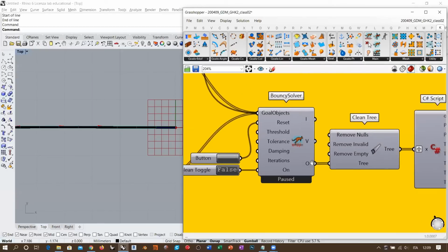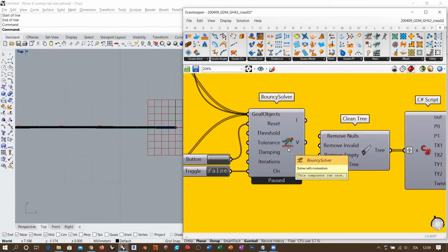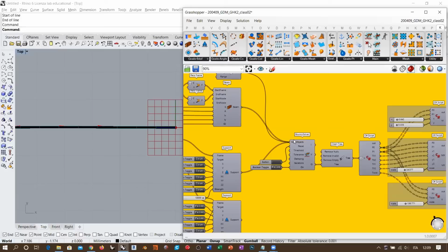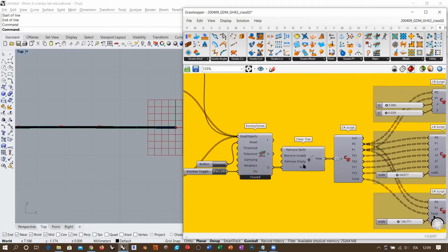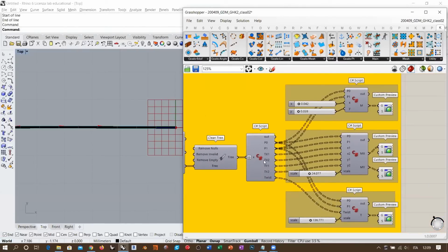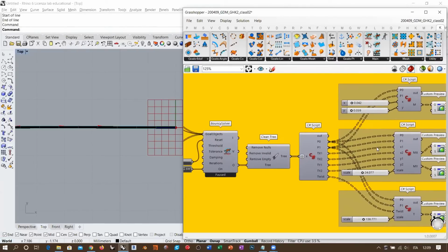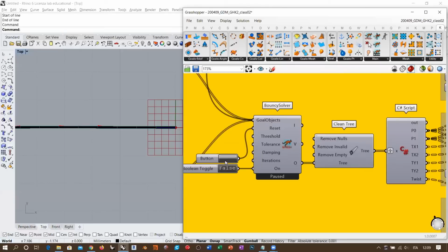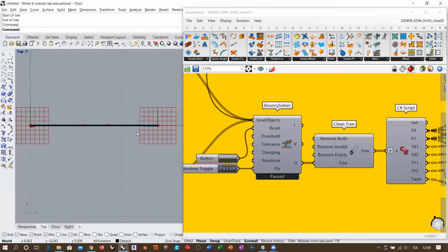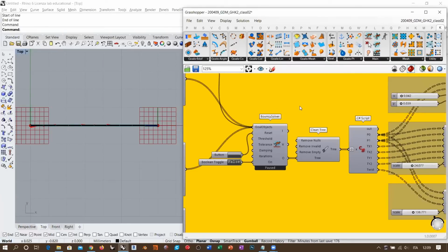The reset in this case, the only thing that it does, well, it resets the geometrical system. But the beam, as you can see, is not by itself geometry, it's its properties. And these properties are used by this script. Then not only do you have to reset the simulation, if you want to go back to the original system configuration, you must also refresh the Grasshopper calculation.